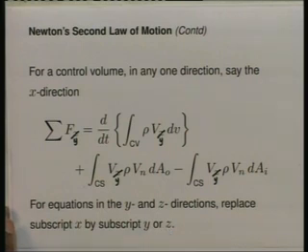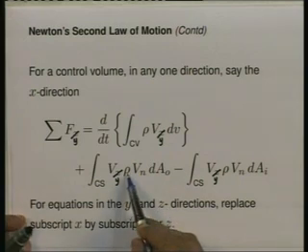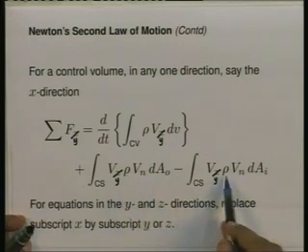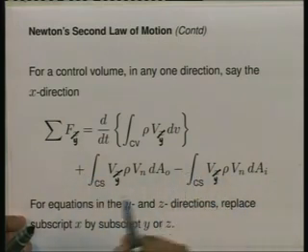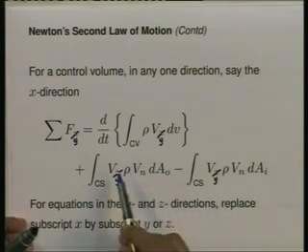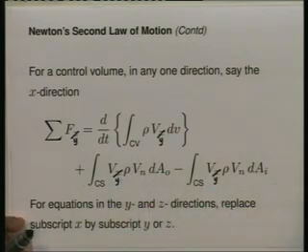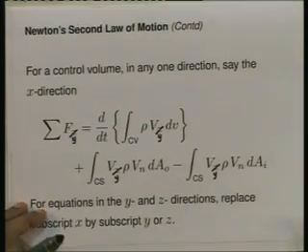If the flow is incompressible, then the rho which is inside the integral can be brought outside the integral sign. We need not consider its variation while calculating these integrals. These are the simplifications we will get if we have incompressible flows or steady flows. So, appropriately the equations can be simplified.